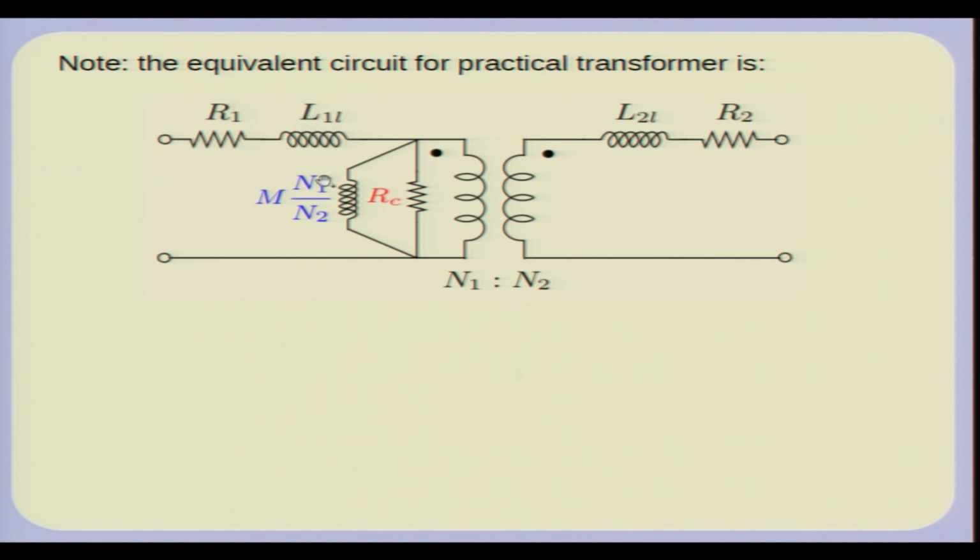Okay. So, by doing open circuit and short circuit tests, you can actually try to infer the parameters of the transformer. What you cannot infer, this is something you can just try to think about. The parameters here are R1, L1, R2, L2 and also this mutual inductance and RC. So, there are 6 parameters and you actually do not have as many measurements. In fact, you can't obtain all these parameters distinctly.